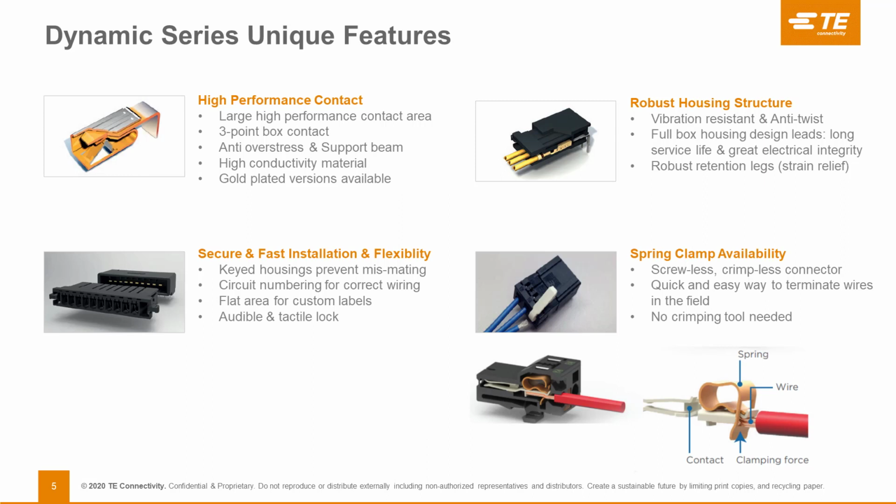Moving on to the next feature, we have secure and fast installation. When we mention secure and fast installation, we are referring to the ease of installation. Where a distinct click sounds, it ensures the connectors are securely latched together, minimizing the risk of accidental disengagement. Additionally, the housings are keyed, as seen in many of our catalogs. The keying positions prevent mismating, simplifying the installation process.